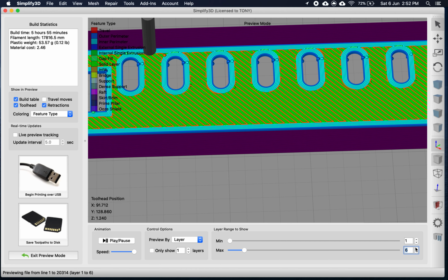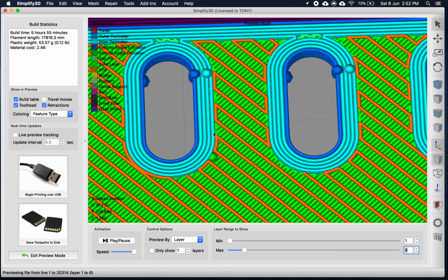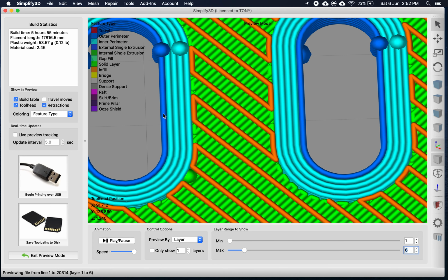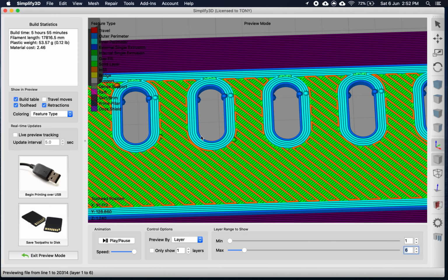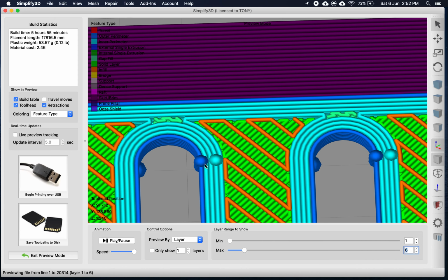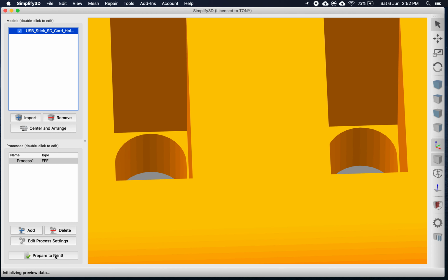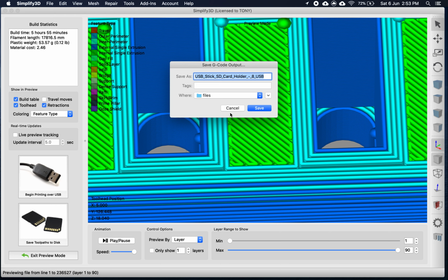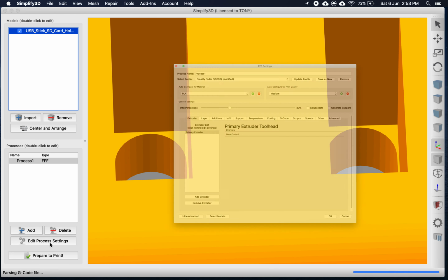Those are the settings for the thickness of a layer, how much you need for the top layer and the bottom layer. And for the shell, if I zoom in over here, you see it will be 5: 1, 2, 3, 4, and 5. So that will be the 5 shell layers. It will be the skin of your parts, how thick you want your skin to be. Let me show you when I change back.